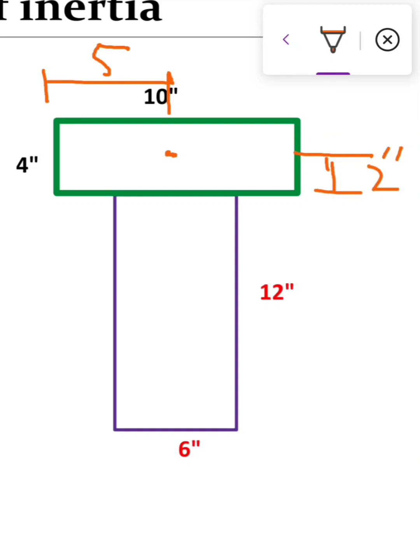We are interested in the along y-axis dimension, because only the along y-axis dimensions are used to calculate the combined center of gravity for both figures. For moment of inertia, we will require the axis to axis dimension, which is along the y-axis.